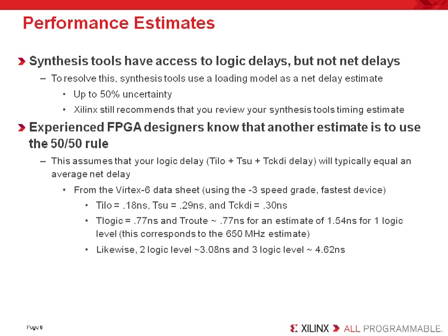Next, you can synthesize the design and then run it through the mapper. That's the first phase of the implementation process, and that's usually gotten through very quickly. So really all the tools have done is taken the design and run it through the mapping or grouping of logic, and then you can generate a timing report that will give you a timing estimate as well. And of course that will use an estimated routing as well. Now the key thing to understand is, again, logic delays at this point are known. LUT delays, register delays, clock to output times on registers, all that's tangible. And in fact, you can find that from the data sheet. But your net delays are not known. And that's really why we say when we're using an estimate, we're working with an estimated net delay.